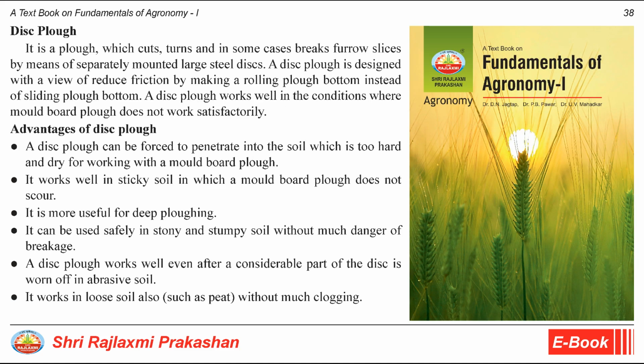Disc plough. It is a plough which cuts, turns and in some cases breaks furrow slices by means of separately mounted large steel discs. A disc plough is designed with a view to reduce friction by making a rolling plough bottom instead of a sliding plough bottom. A disc plough works well in conditions where a mould board plough does not work satisfactorily.